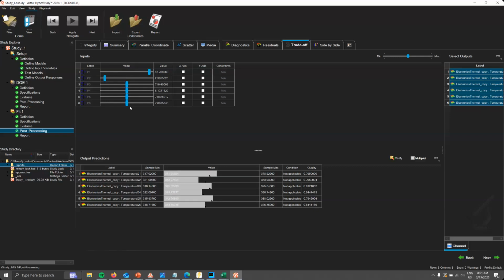right? So it's not just the relationship between this transistor's dissipation or loss and its temperature. It's also the relationship between them, the fan in action, the heatsink in action, the PCB also dissipating a bit of power or sharing a bit of heat between these devices. So this model can be nicely exported onto a block, which we can use in a system level simulation. And it is practically the same thing.